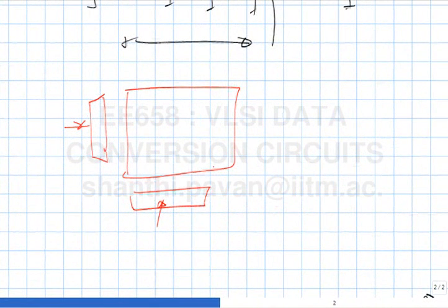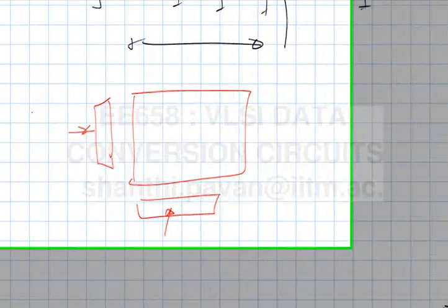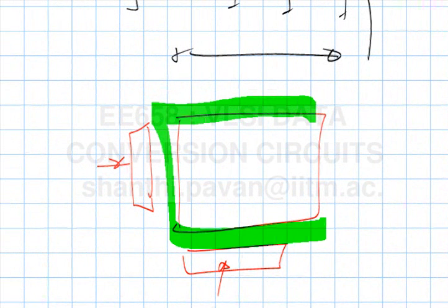in really high precision converters there is an additional problem, and that relates to the fact that this is not going to be a small thing, right? This is going to occupy some space, and all process variables like threshold and oxide thickness all have some kind of, I mean, they are not absolutely constant across the die, right? So the zeroth order approximation is that everything is constant, Vt is constant across the entire area of the current sources. The first order approximation is what?